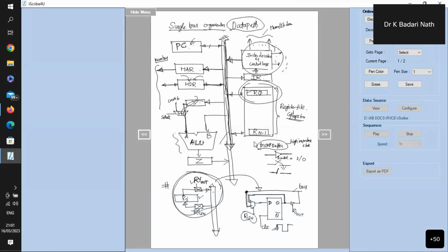So now we have identified control signals for all the different blocks present in the processor, so that at my request I can enable any of the blocks for writing, and on my control I can enable any of these blocks for reading. These different control signals are generated by the instruction decode and control logic based on the instruction stored in the instruction register. Now we will go into a little more detail on how exactly instructions will be executed based on these control signals.